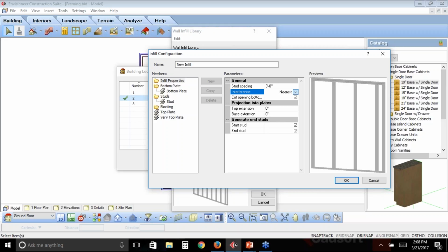So what do I do with that stud that's going to interfere with this other wall that's coming in and its corner configuration? Do I move it to the next nearest location, or do I remove it and just delete it altogether? You've got that option depending on how you'd actually frame it. If that spacing hit on a corner, would you just move it beside it, or would you just get rid of it? You can make that choice.